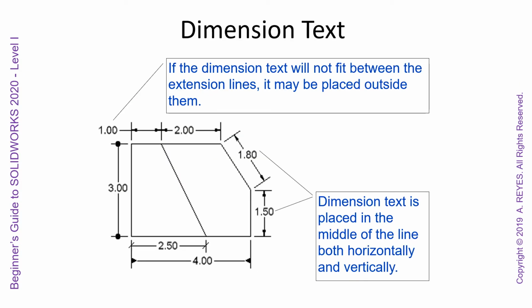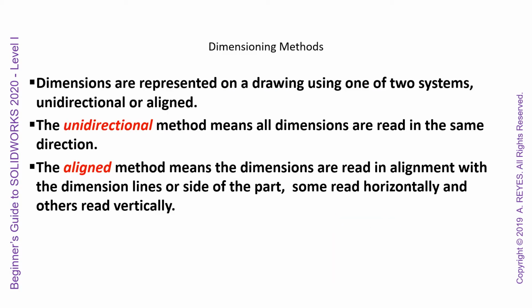Dimension text. If the dimension text will not fit between the extension lines, it may be placed outside of them. Dimension text is placed in the middle of the line, both horizontally and vertically.